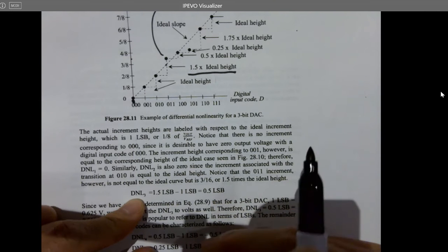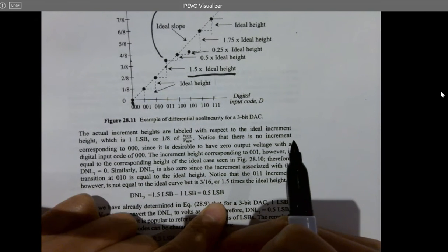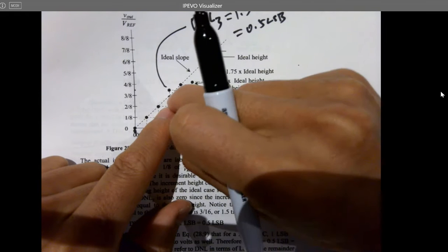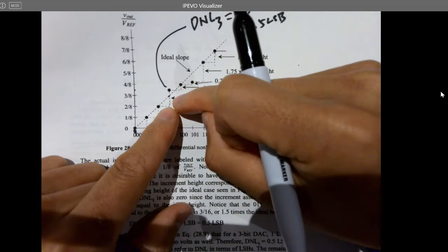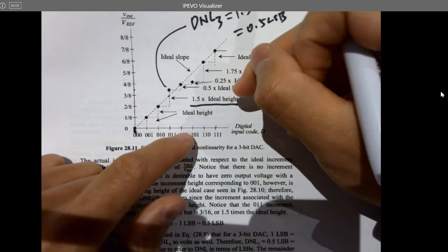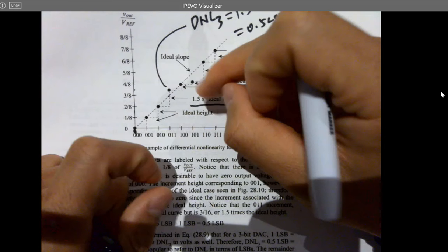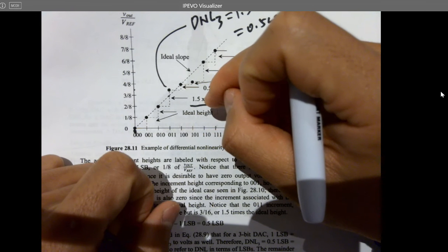Differential nonlinearity. Yeah, you can understand it that way. It's just errors. You are supposed to get this point, but actually the output is a little bit higher. Sometimes it can be lower. So that's the errors, because all the circuit components are not ideal. They have tolerance, like resistors, plus or minus 0.5% or something.